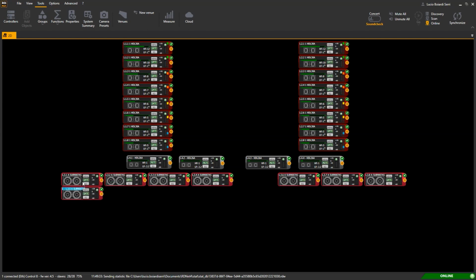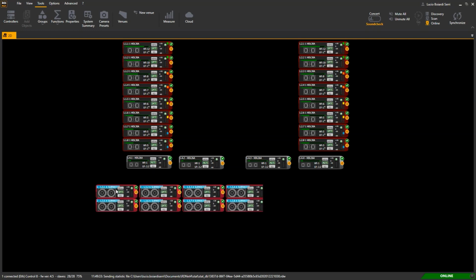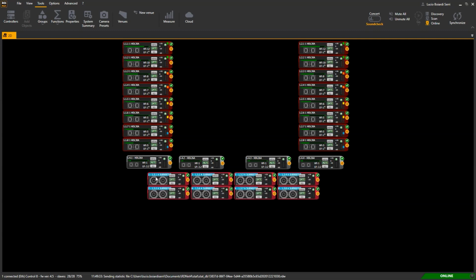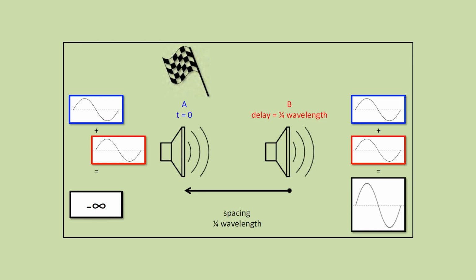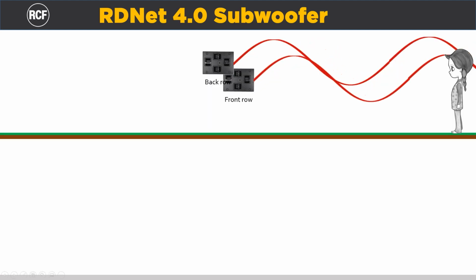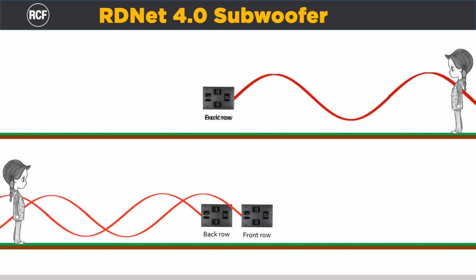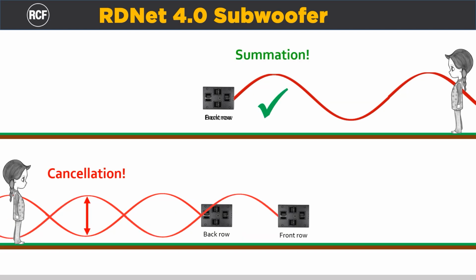There's another option to control subwoofer directivity: end-fire or gradient configuration. This configuration is achieved by aligning two subwoofers or two subwoofer arrays in the same direction and placing them in front of each other. Subwoofer A is delayed to virtually overlap subwoofer B. This way allows the maximum sound pressure to be obtained and the cancellation of a part of the sound spectrum behind the speaker. Typically, the frequency wavelength at which the cardioid effect, so the cancellation, occurs is 4 times the distance between the speakers.